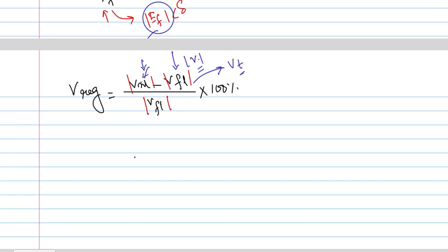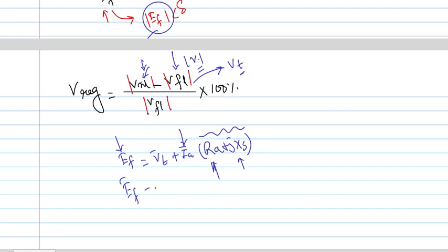Then we have to go for these equations. The EF is nothing but your Vt plus Ia into Ra plus j Xs. Now, if we are able to measure the machine's armature resistance and synchronous reactance, then we can find out for a particular load what the generated EMF is. This generated EMF is equal to Vt when my armature current is 0. That means it is an open circuit condition, so this Vt is nothing but your Voc at that particular instant.